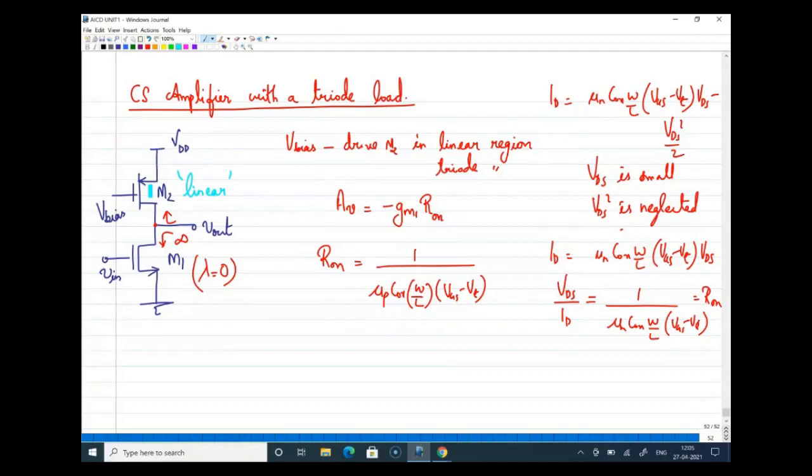I'll tell you what are the other reasons. You can see that from this expression, the on resistance is having mu p. So mu p is something which is not a constant. It can slightly vary. It depends on temperature, because mu p varies with the temperature. You will also see a variation in VT. Threshold VT also can vary in a MOSFET. Now, if mu p and VT vary, I can say R1 will vary. That R1 is a variable.